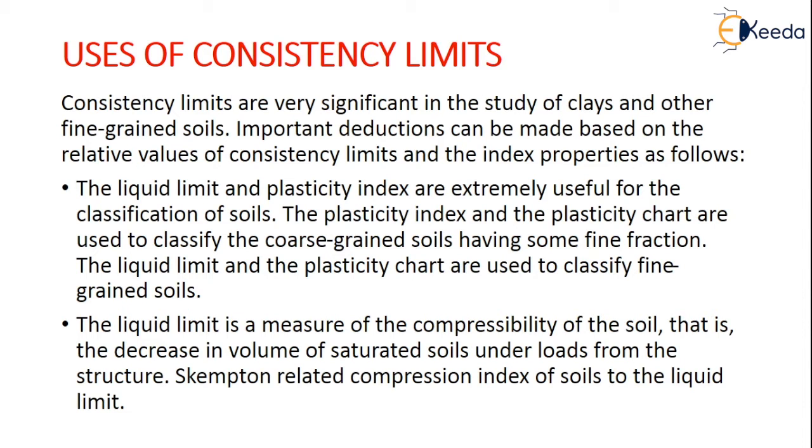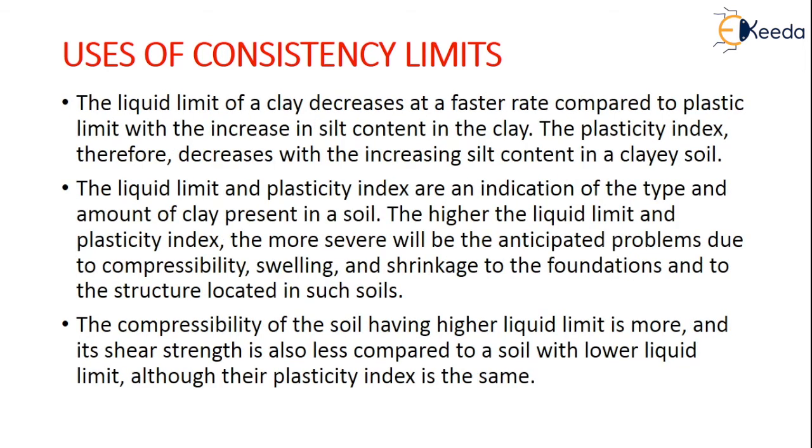Coming to the liquid limit, it is a measure of the compressibility of the soil, that is the decrease in volume of saturated soils under the loads from the structure. Skempton related the compression index of soils to the liquid limit, which is very important. The liquid limit of a clay decreases at a faster rate compared to the plastic limit with the increase in the silt content in the clay. So the plasticity index therefore decreases with the increase in silt content in a clay soil.